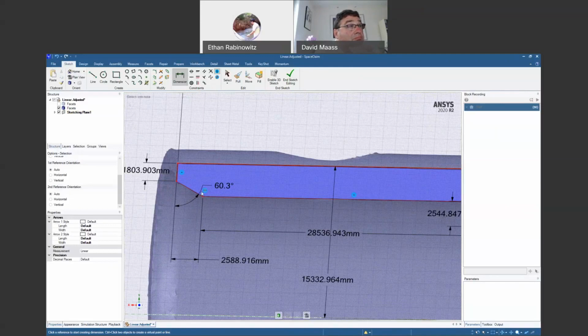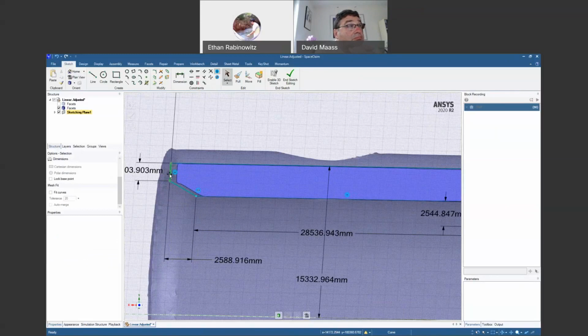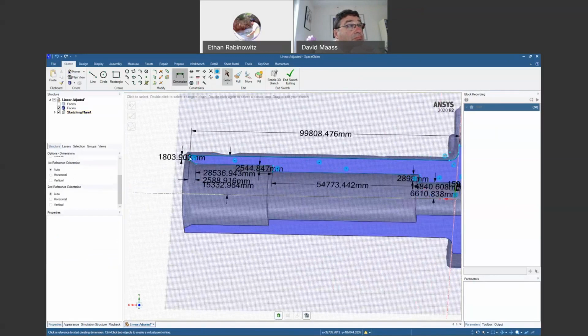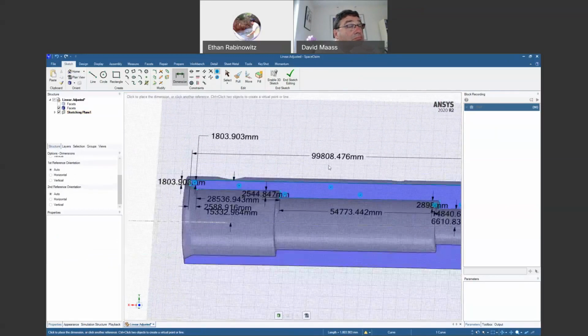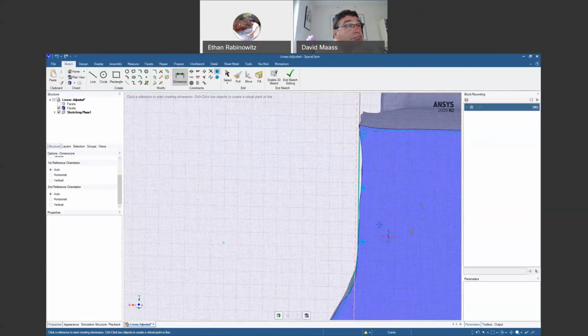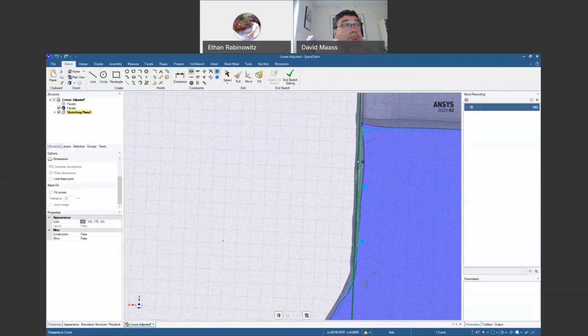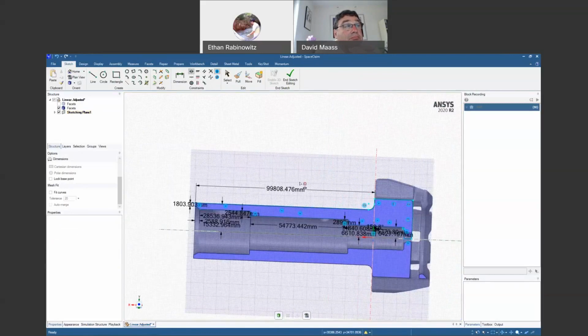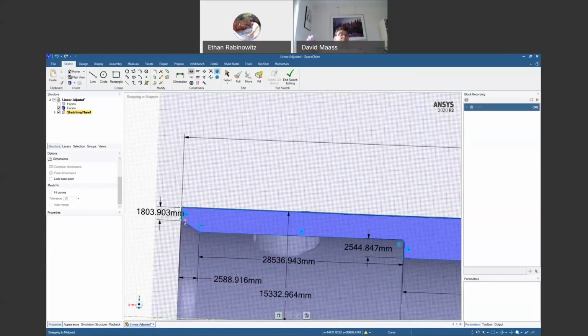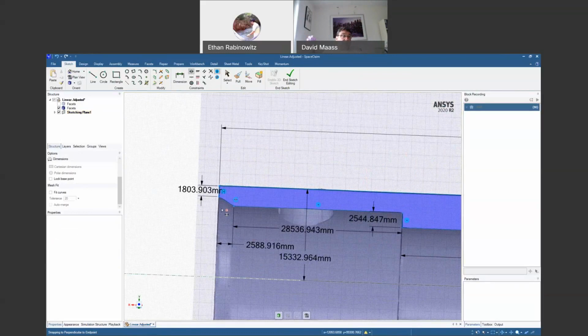I'll take off this angle here. Now let me just drag it. Okay, so what I think I want to do, yep, I could dimension where this line is off. All right, so here's what we probably want to do. This face right here is right along where this axis is. So it probably makes sense to constrain that face to that axis. And then that actually constrains this, because this is now constrained essentially to this axis. And now we're all fixed up here.